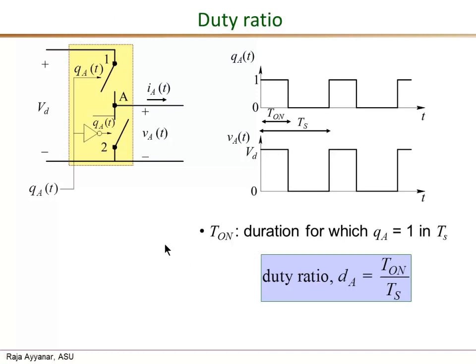Duty ratio is an important factor, since in all the converters the duty ratio of the bipositional switch, or possibly several bipositional switches, is the main control variable to meet any given control objective. The duty ratio will be continuously varied by closed loop feedback control to meet any objective as the operating conditions change.